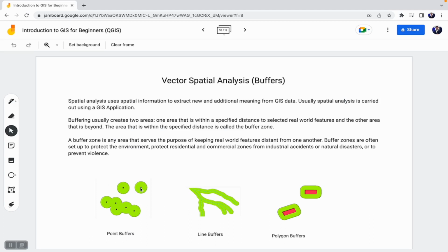For example, you want to site a school. Most people use buffers for planning purposes. One of the criteria would be that it be 50 meters away from a major road, so that it will reduce noise. So with buffers, you can generate a buffer from the chosen location and examine what falls between 0 to 50 meters radius. So that's one of the uses of point buffers.